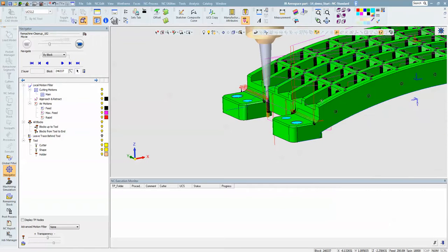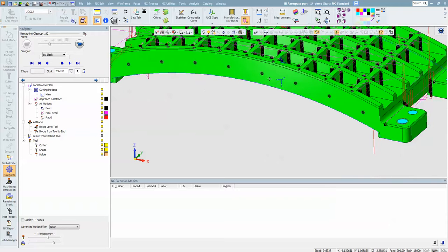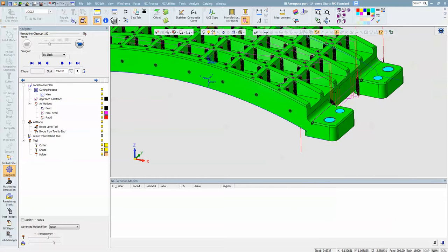You can have up to 6 different lengths of the same cutter and tell it to go cut a job. So you can have a short rigid cutter, a standard length, an extended length, and a stupid extended length, all with different downstep, RPM, feed rate, all independently controlled within the same one procedure, all divided up according to the software.